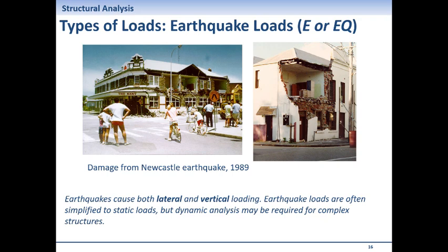And lateral or horizontal motion is another. It translates to pushing the building in one direction in a fraction of a second, and then pushing the building in the opposite direction, and then in the perpendicular direction, and then in the other direction. So it's really complex in terms of loading, how the load itself behaves.